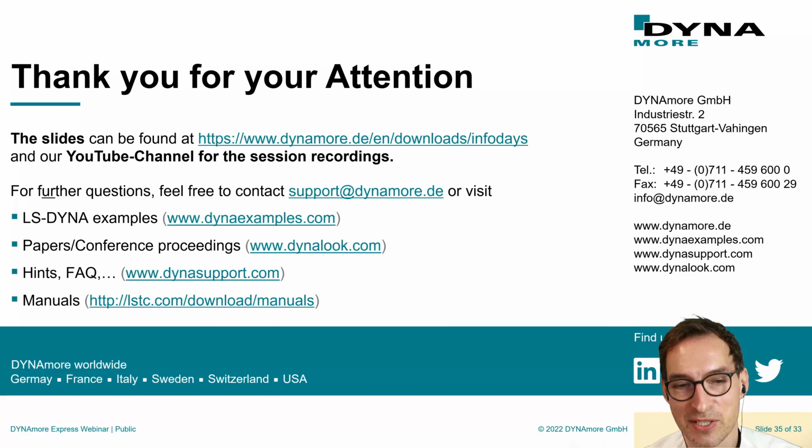Okay, there's the last question. Which method is best suitable for internal blast explosions? Simple conweb or ALE? I don't know conweb, so ALE. I really don't know what conweb is. I never heard of this one. I saw a couple of people, also my colleagues from DYNAmore Swiss, just recently do an explosion simulation in some mining underground facility, looking at the distribution of pressure waves inside of the facility. They were working with ALE, and got good results with this one. And there's a comment from my colleague: material models for ALE are stated in the keyword manual. Just check it.